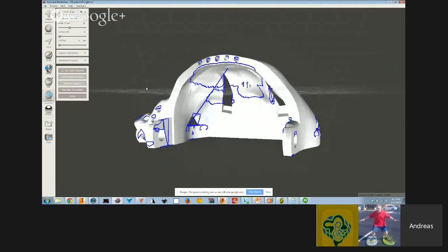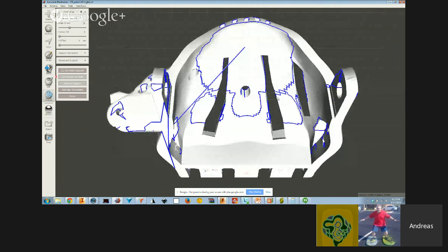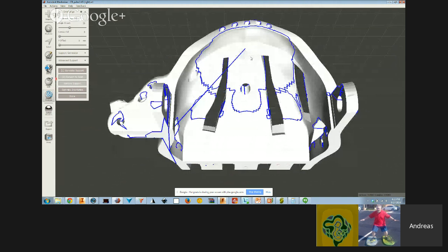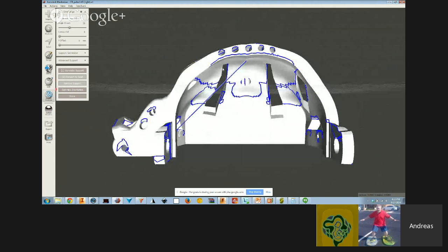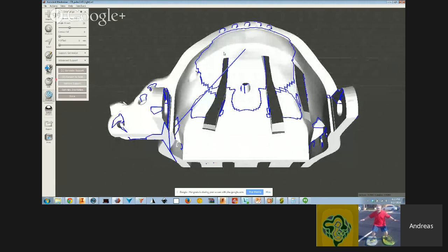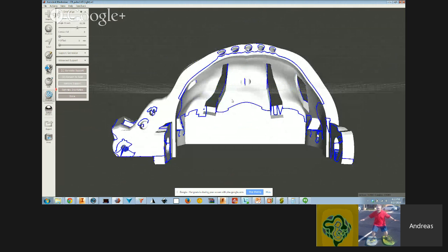Is everything looking correct? The shader doesn't look quite the same as on my computer, but basically, what I see on my computer is the overhang area is highlighted in red, and threshold. So as I increase this angle threshold, you'll see that the blue boundary, or the redness if you have red on your computer, will increase.